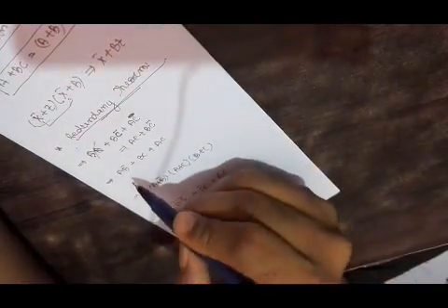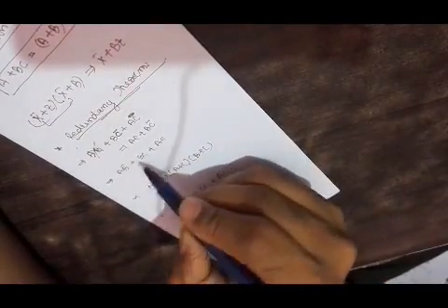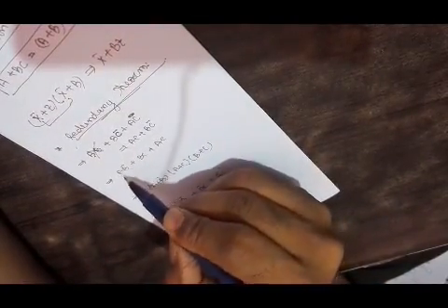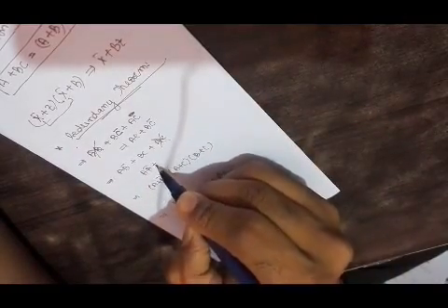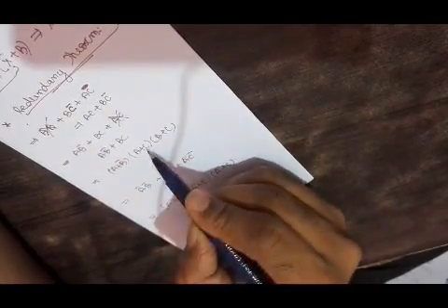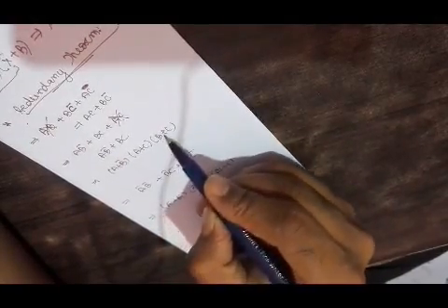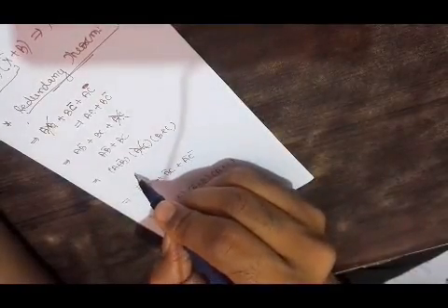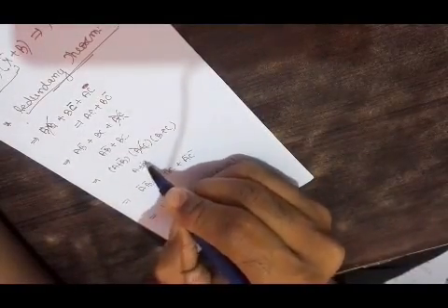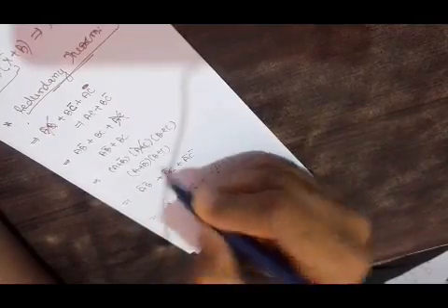Right? Similarly, here you see b and b bar. These two terms are undergoing some variations. So apart from this, the remaining term is a redundancy term. A b bar plus bc is the final output. And here we see a plus b bar and again b bar, and here is b. So these two terms are undergoing variations. So this is a redundancy. So a b bar and b c is the output.